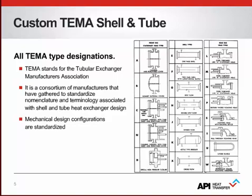A K is strictly for shell side vaporization with low pressure drop requirements and can also be useful for a stage of separation in distillation applications. Essentially the vapor-liquid mixture is separated within the K shell and the bottoms are drawn off while the vapor re-enters the column through the top. And on the rear head, the L, M, and N styles have the same features as the A, B, and N front heads we just discussed. And because of that, they're often paired together.